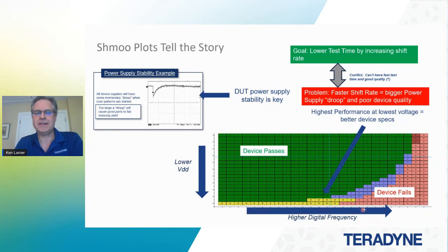And so you can expect that as the VDD goes down and the test frequency goes up, you'll eventually get failures and you'll get passes in the opposite condition. And then there's sort of this area in the middle where sometimes it'll pass, sometimes it'll fail. So it tends to be a little unstable. And what we really want to do is the farther out we can get this failing region, farther we can get it down into the right, the better.